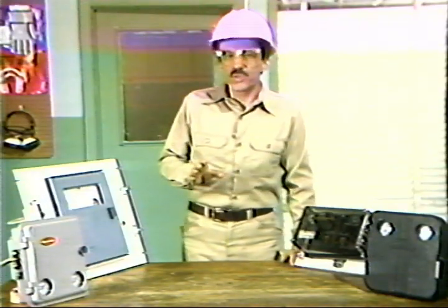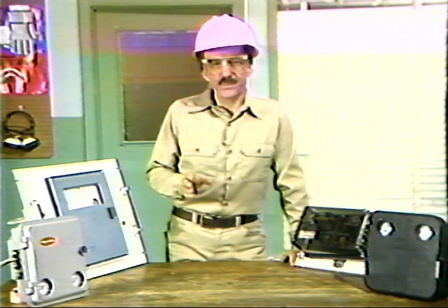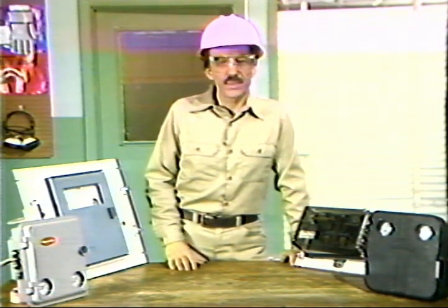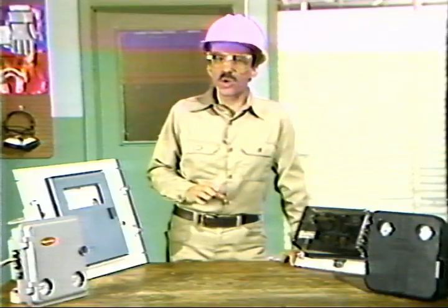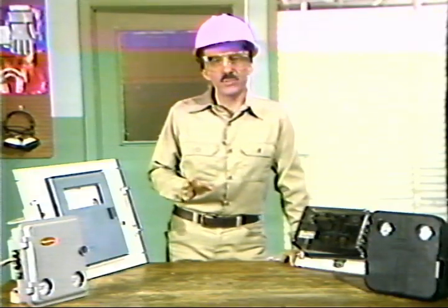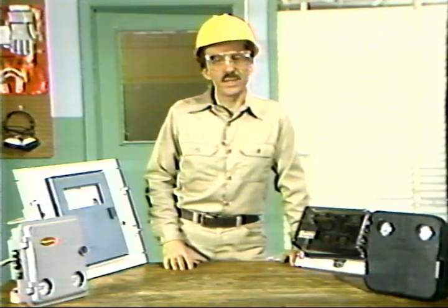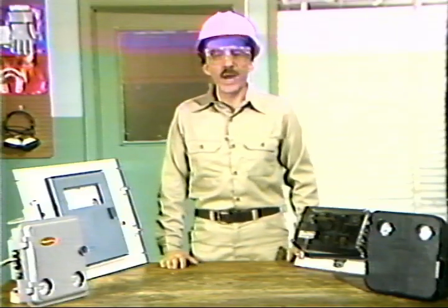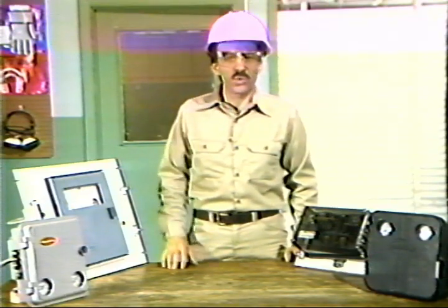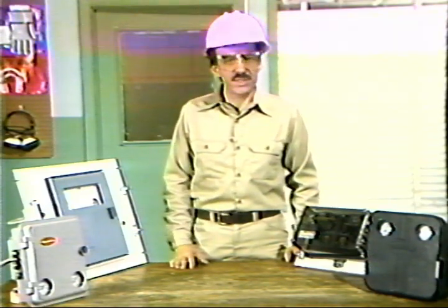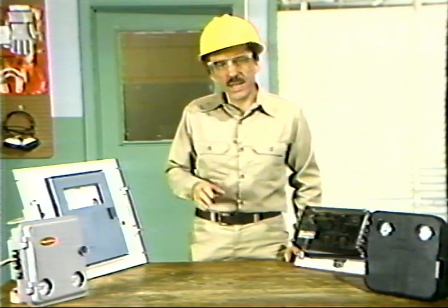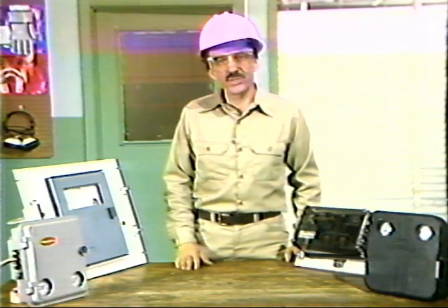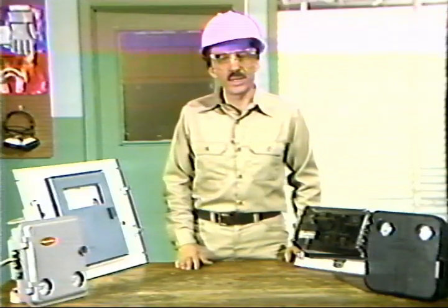Each of the control modes we've just examined has its good points and its limitations. For example, even though a three-mode controller may seem to be the best one, it's too sensitive to be used in some processes. You're likely to work on pneumatic controllers that provide one or all of the control actions we've just discussed. What makes these controllers different is the way their internal mechanisms are arranged to provide these control modes.